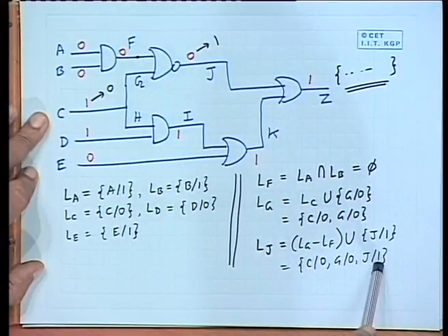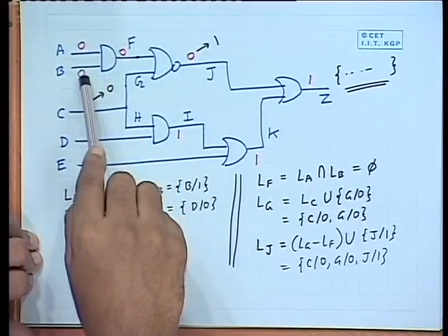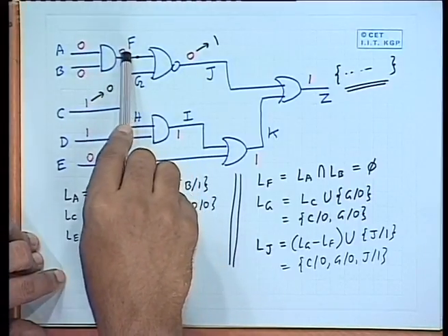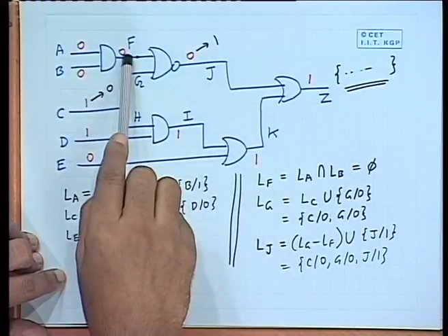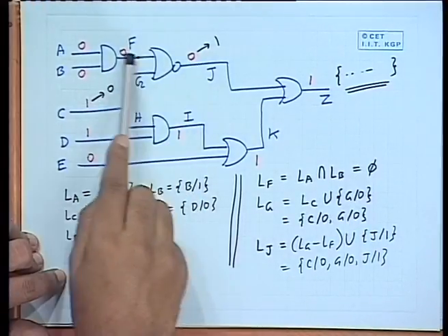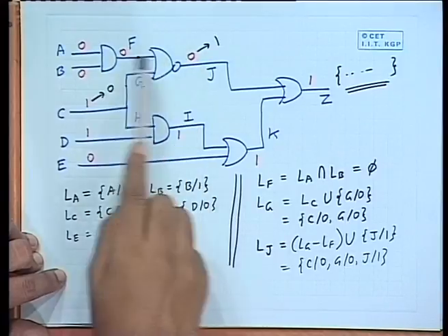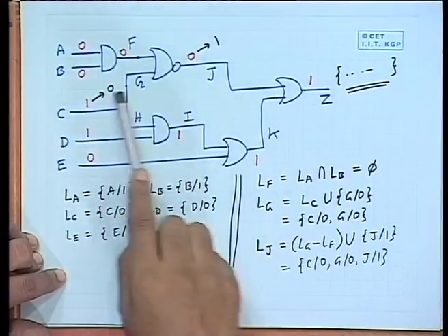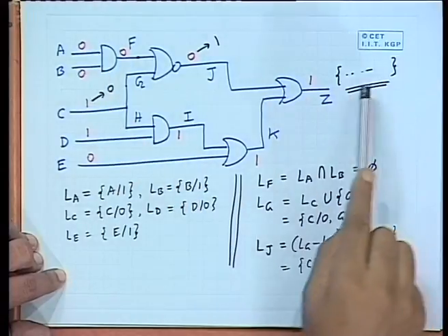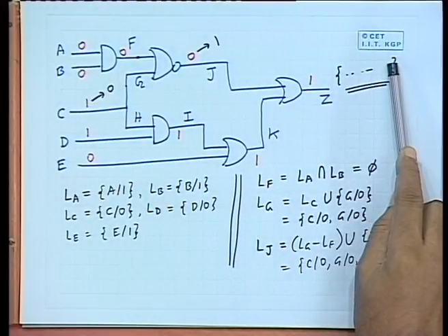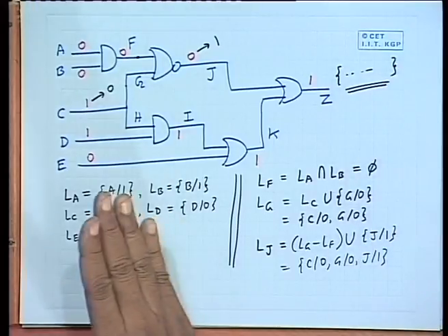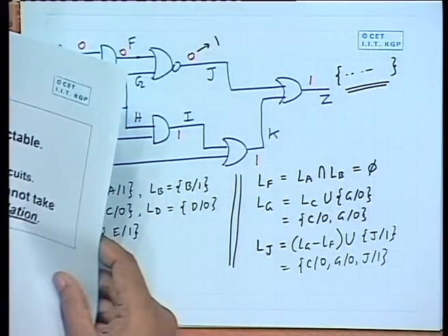You retain them, and wherever in the circuit there are changes in the logic value, you recompute the fault list. And if there is a list event, you propagate that list event to the output of the next gate in sequence and you redo it. So, you will find that in the next step again you will get some other fault in the Z. So, there will be some faults detected. So, this is how this method works.